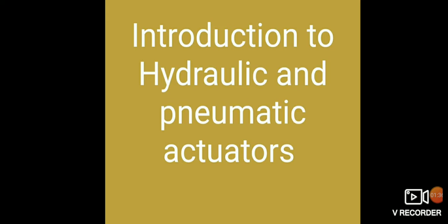Hydraulic actuators are classified as linear actuators and rotary actuators. For linear actuators, hydraulic cylinders extend and retract a piston rod to provide a push or pull force to drive the external load along a straight line path. For rotary, continuous angular movement is achieved by rotary actuators, more generally known as hydraulic motors.